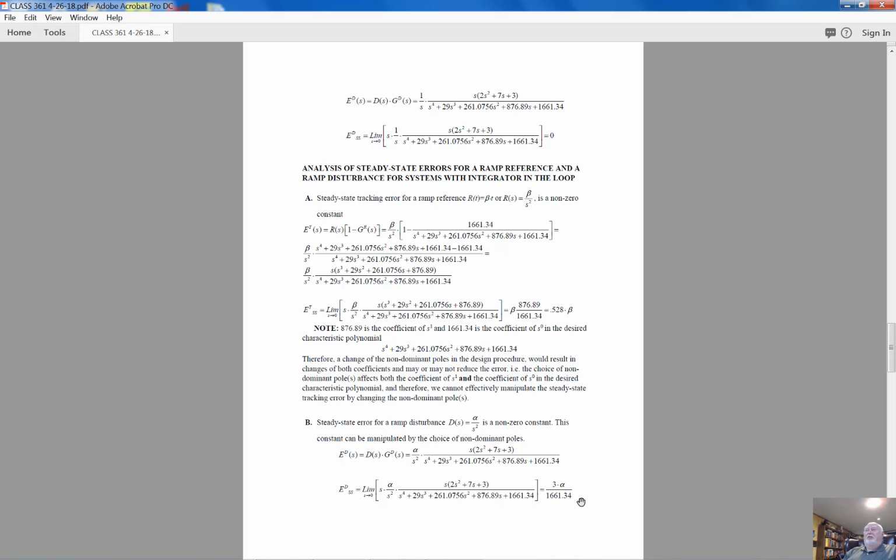And you know what's good about the pole placement procedure? If you were doing this with a controller designed differently, we would be concerned about system instability. It's not the case. A system will stay stable regardless of how much you change the non-dominant poles.